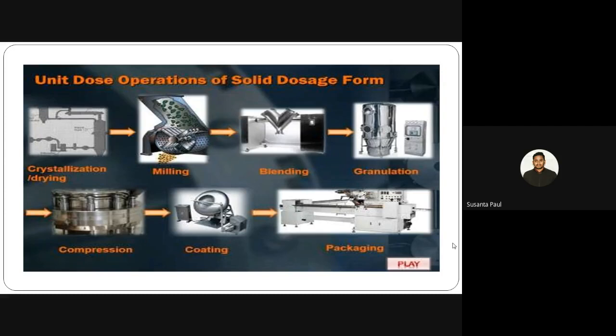The powder of higher density forms an upper layer, so it is not possible to get tablets of uniform composition. In case of granules, they may be bigger or smaller but are uniform in composition. The ingredients are bound together and cannot separate. Therefore the separation of the smaller granules at the bottom is not going to change the composition of the tablet. So this is the basic difference between the powder particle and the granules.